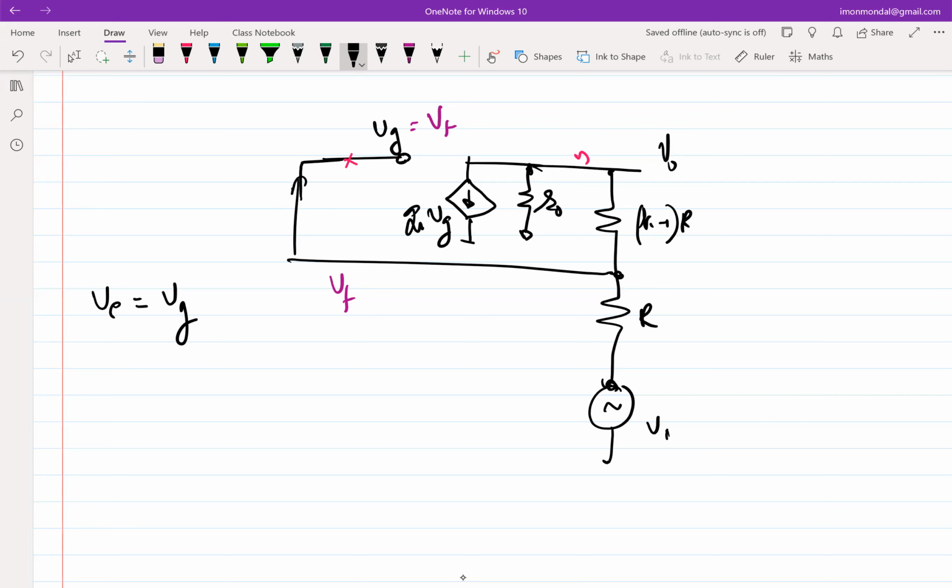It shouldn't surprise us because, what is the transistor? The incremental gain of the transistor is GM times VG minus VS, right? It is a difference amplifier. It amplifies the difference of two voltages. So when I put that difference amplifier in negative feedback, and as long as the amplification factor is very high, we would expect that difference to go to 0, right? So the error voltage is that difference, whatever it is amplifying. Okay, so in this case, since the source is grounded incrementally, the difference is the gate voltage itself, right?